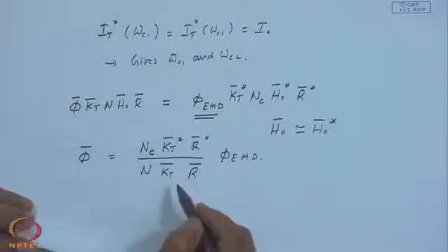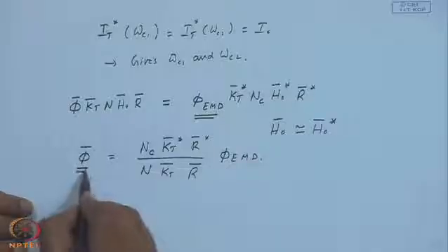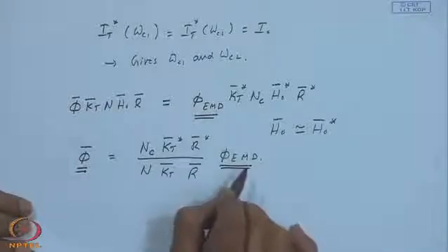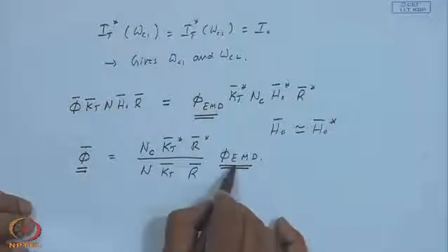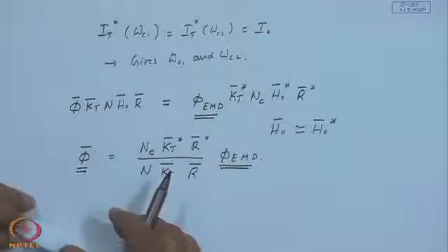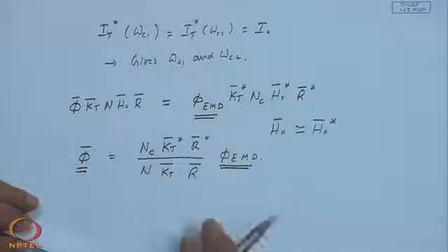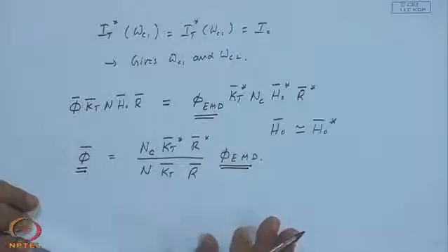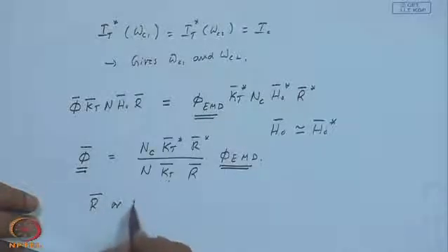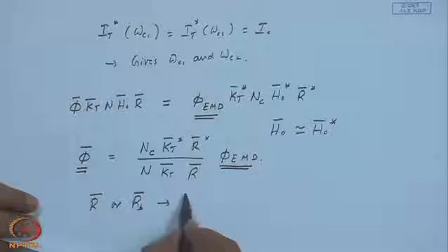So, the sum and substance is the monthly average daily utilizability has been related to utilizability of a single day, and that single day being called the equivalent mean day, the properties of which are the clearness indices are always above the clearness index KT minimum and the average is KT bar star. So, the question of IT minus IC being negative on any of these days does not arise. So, basically the analogy, if you recall from your R bar or RB bar, there the averaging works.